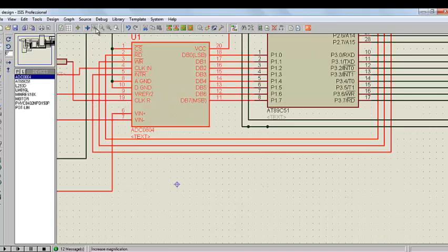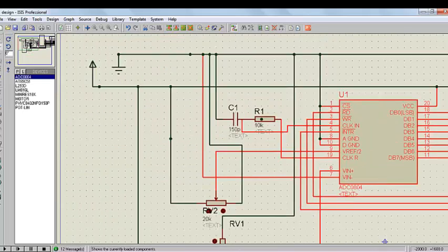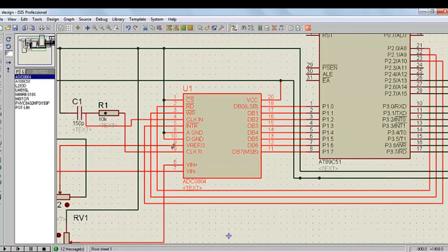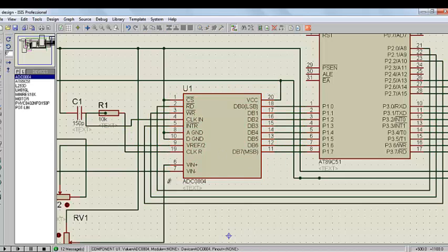That's an 8-bit analog to digital converter, and it can convert only one analog input at a time. So this is what the pinout of the 0804 looks like. It requires a V reference. Basically, it requires half of the reference voltage. It's an internal configuration, so I don't know why it requires half of it.